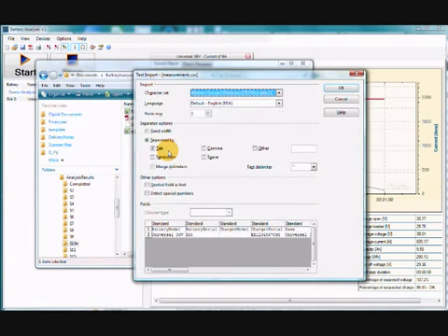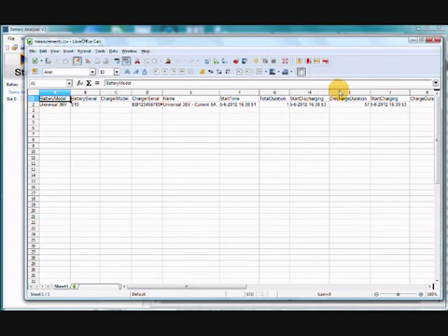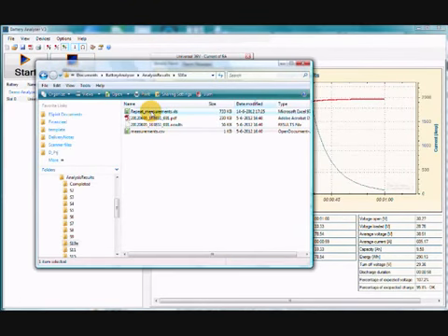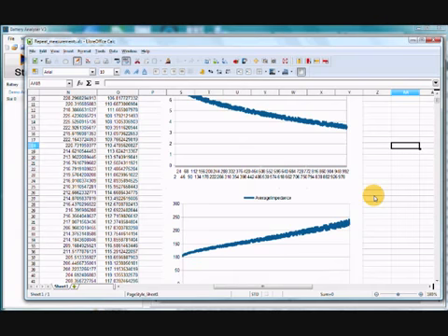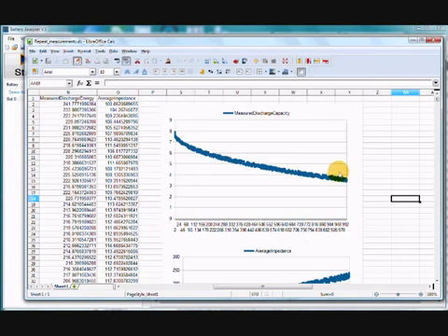This CSV file can be read by Excel or LibreOffice Calc as a spreadsheet or by a statistical program for further processing. If a battery is tested in repeat mode, say 1000 times, there will be 1000 results lines in the spreadsheet. The spreadsheet here has the repeat mode numbers, and I have made plots from the capacity and impedance columns.